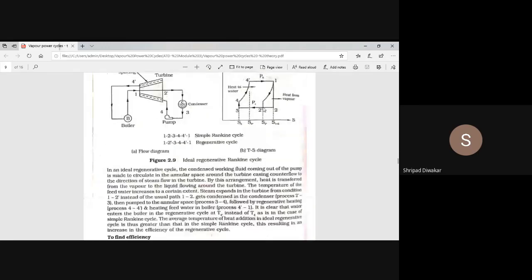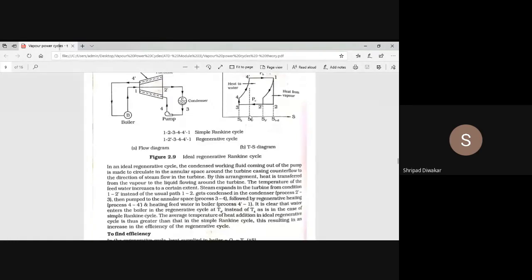From the diagram, (S2 dash minus S3) divided by (S1 minus S4 dash) in the ratio QR by QS, but the denominator is exactly equal to the numerator, both are the same because of the parallel lines. These two get cancelled. So QR by QS is T2 by T1.